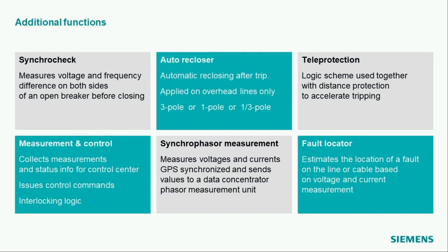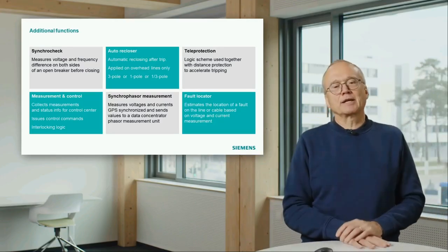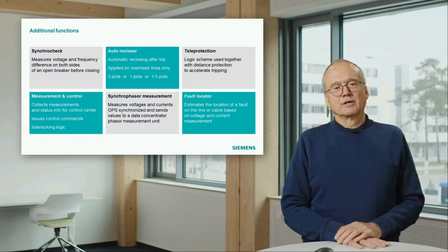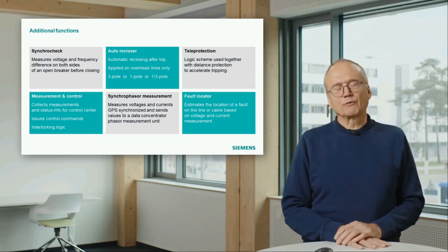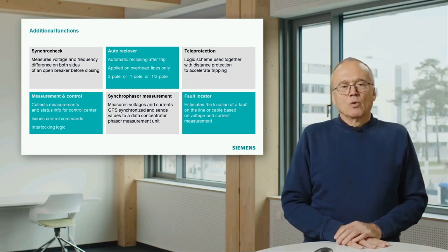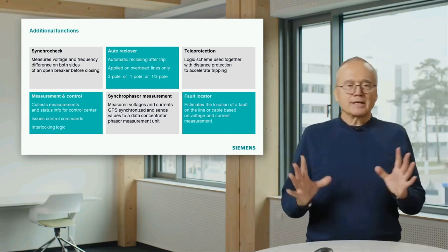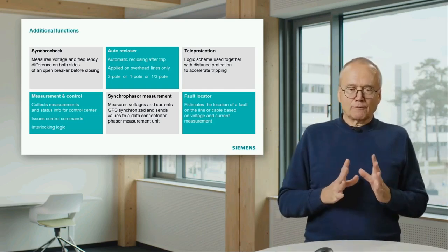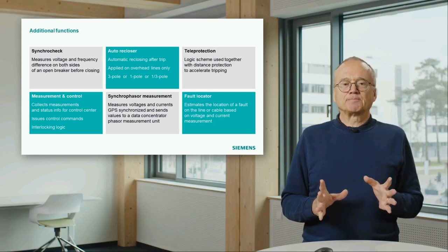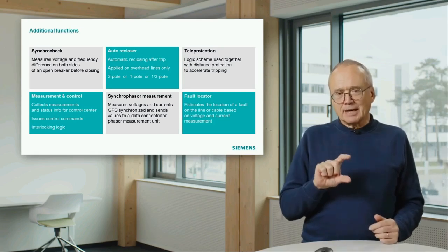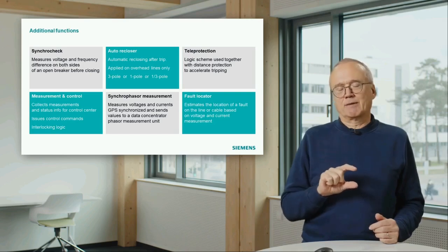And the last thing I would like to mention here is a relatively new issue. You find it since decades in many papers, but the area of application is growing. It's the so-called synchrophasor measurement. What is that? That is a measurement of currents and voltages, but very precisely with phase angle and magnitude and a timestamp.